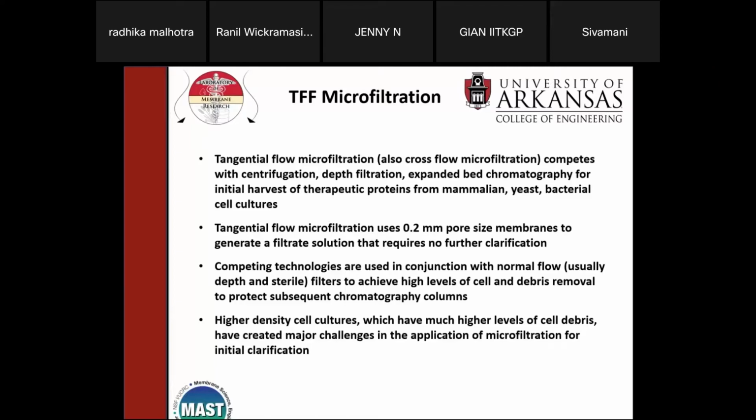It's basically the reversible buildup of rejected species near the membrane surface, and I'll show you more of that in a second. These phenomena are avoided by operating at low filtrate flux below the critical flux for fouling and/or exploiting inertial lift effects. So let's put a diagram here and try and explain this.